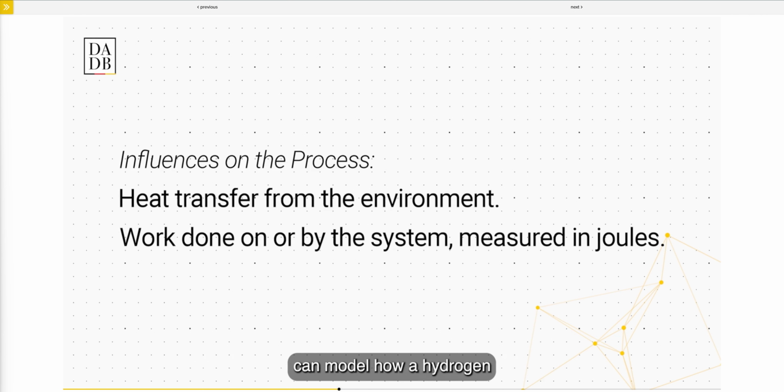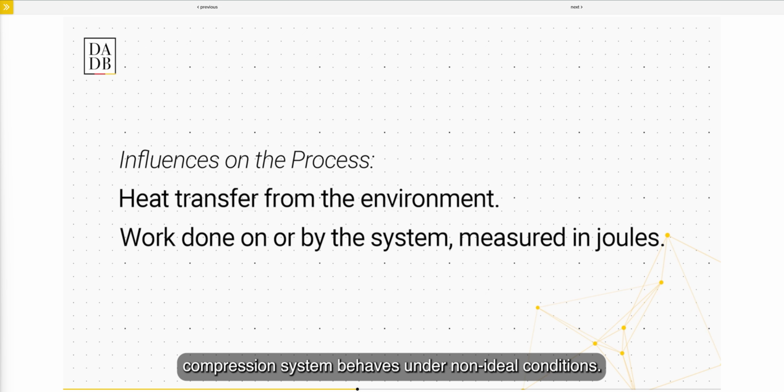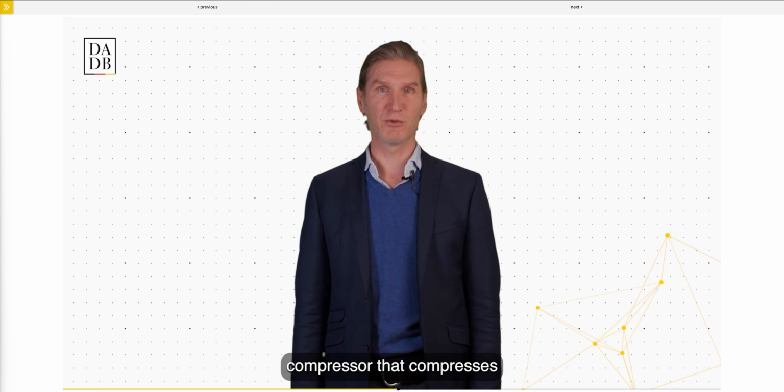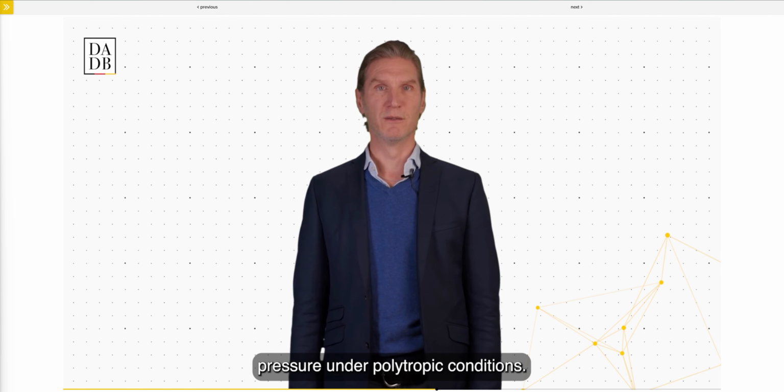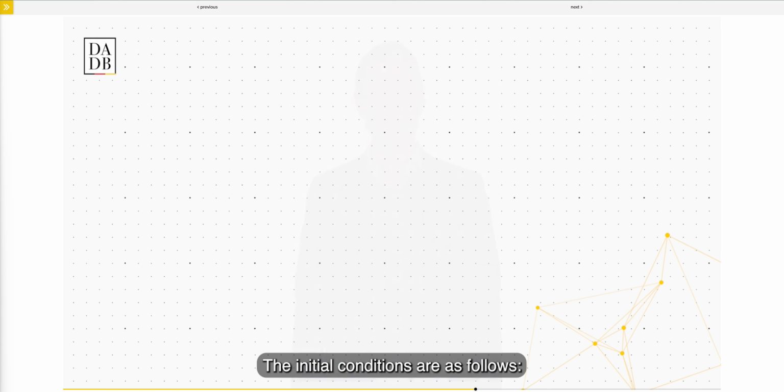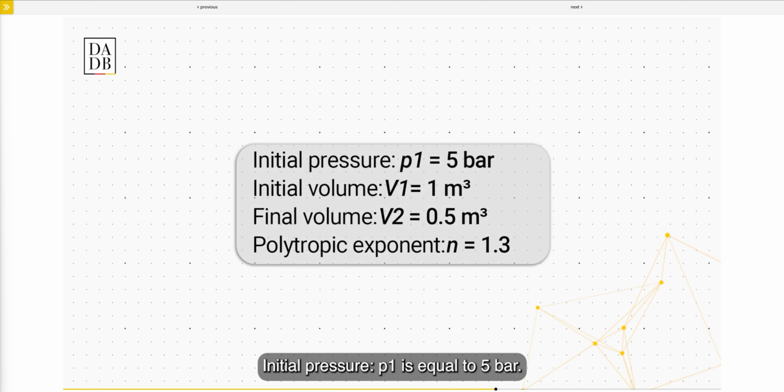Using a polytropic approach, we can model how a hydrogen compression system behaves under non-ideal conditions. Let's consider a hydrogen compressor that compresses hydrogen from a lower to a higher pressure under polytropic conditions. The initial conditions are as follows. Initial pressure, P1 is equal to 5 bar. Initial volume, V1 is equal to 1 cubic meter. Final volume, V2 equals 0.5 cubic meters. Polytropic exponent, N is equal to 1.3.